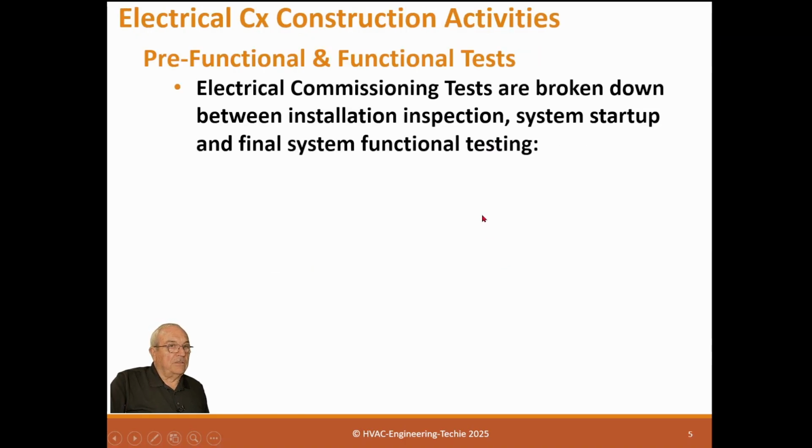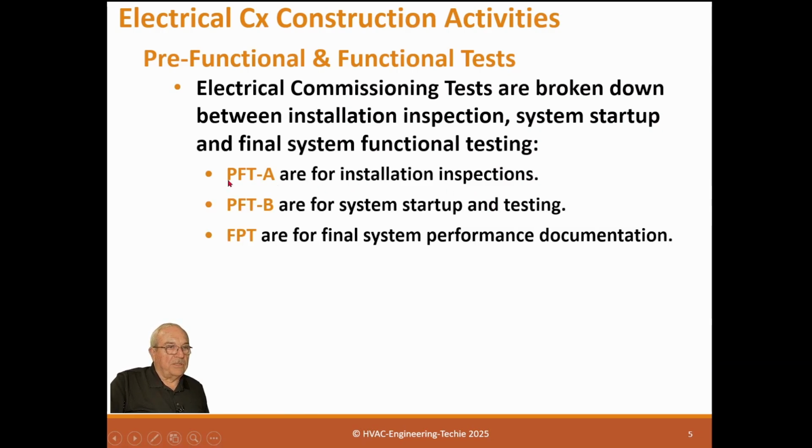Pre-functional test. Electrical commissioning tests are broken down between installation inspection, system startup, and final system functional testing. Now, it's kind of irritating, but when ASHRAE created this term, pre-functional test, they didn't realize that there's actually 2 types of tests in that. One is a pre-startup test, and one is a startup test. Well, I put A and B on them just so we could keep them clear. It's very confusing if you don't understand that there are 2 different types of tests and they put the same name in both of them.